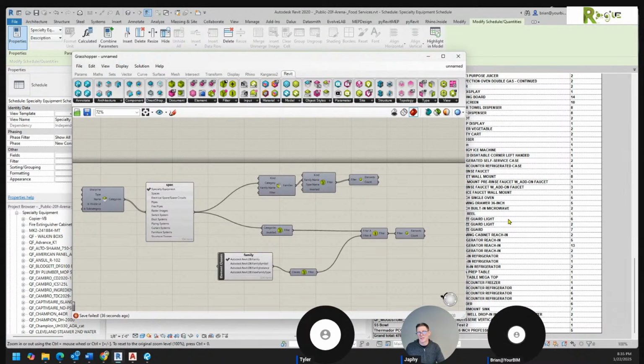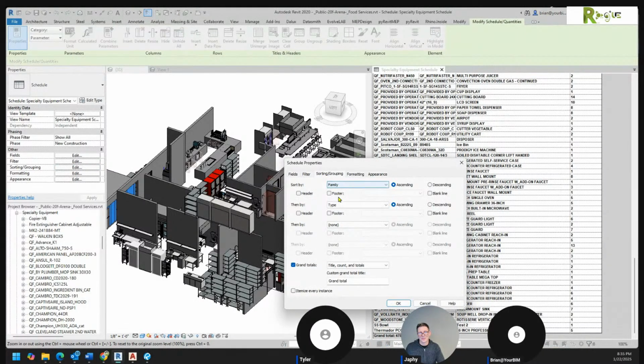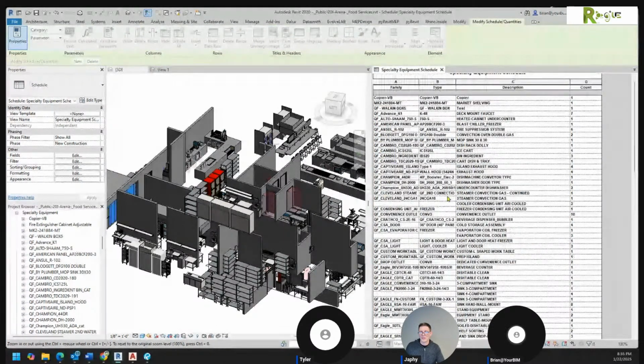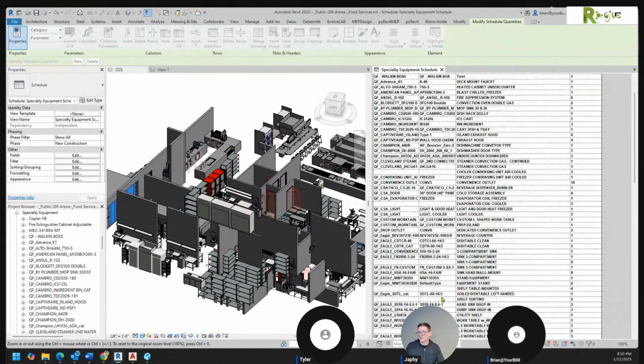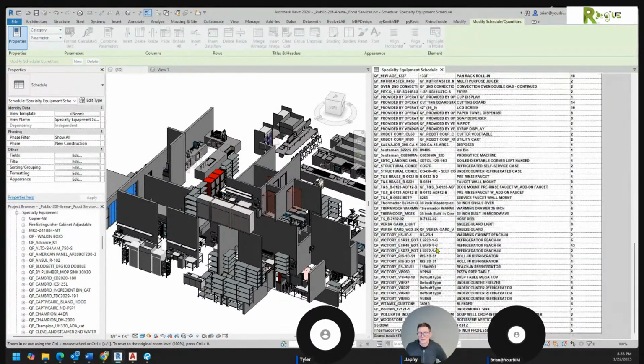Oh, you can. Well, listen, dude. Watch how easy it is for me to identify the names. All I have to do is say sorting and grouping. Yep. And just sort by description. And anywhere the family name is empty means I've got multiple family names. See, I've got 3 different objects here that have different families. See how that name is different? Yep. So I'll just go through and fix those handful of guys so I don't have any duplicates.